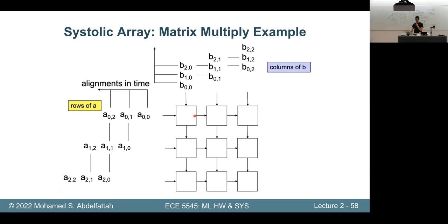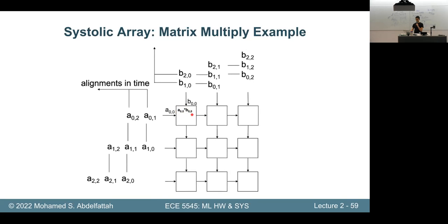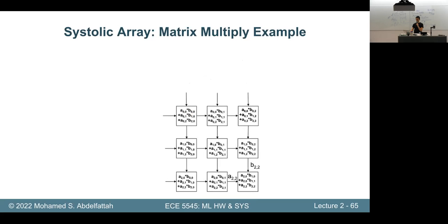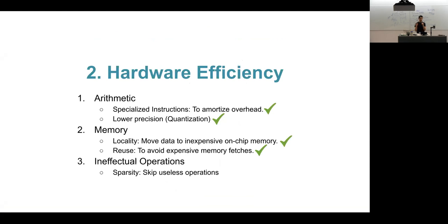So if you look at this first box, this is the partial sum, and then I'm adding to it something, then I'm adding another thing, and so on. So this is output stationary. And so it's neither input nor weight stationary. You will find, like I said, both output and weight stationary are quite common. And you'll find weight stationary prevalent especially in mobile chips, where you do a lot of convolutions. So you have a lot of reuse of weights, and so you would store the weights and perform convolutions very efficiently.